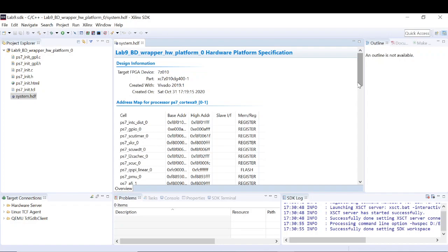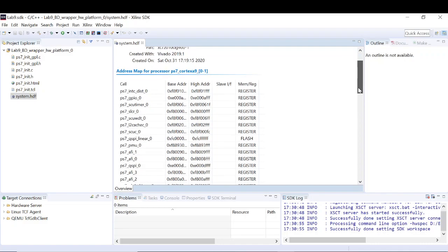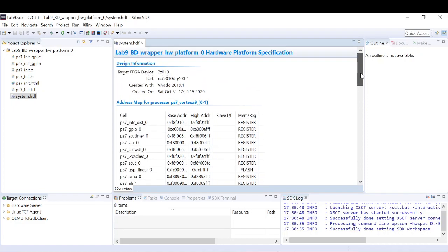In Zynq SoC, everything is memory mapped. I'm not going into the detail of it because this will be covered in the lecture in detail. For timing, what you can see is that everything in the Zynq is associated with some memory location, like how to access any port or any peripheral, for example USB, for example SD card. Everything is assigned a memory location, right? Not a single memory location, but a range of addresses. As you can see, this is the base address and this is the highest address. Similarly, for this timer, for general purpose IO, we have this base address and this higher address.